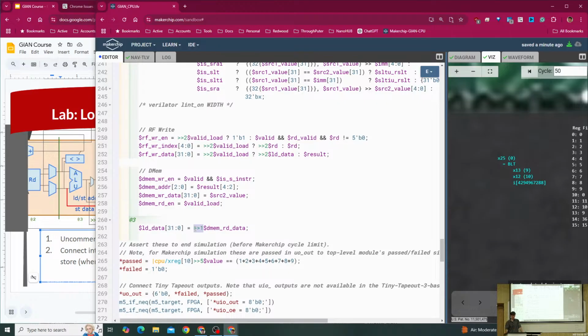And likewise for behind. Whereas the stages is just a question of when you're performing computations. So anytime you change the relative reference, the ahead by, behind by, that's going to change functionality. Anytime you change the ats, that's going to preserve functionality.